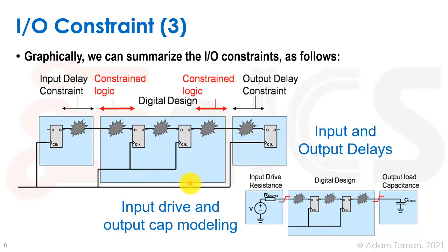In the output, we actually add negative skew, because here, again, this is going to stay ideal with 0 time, and this is going to get some clock propagation, which is going to make the clock arrive at the launch path later than the clock arrives at the capture path, and that's going to be negative skew, and it's going to make our timing harder to meet.